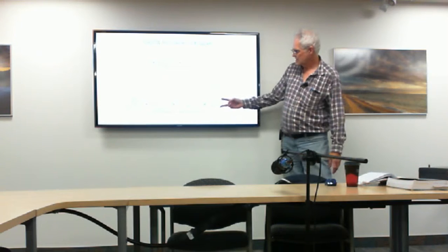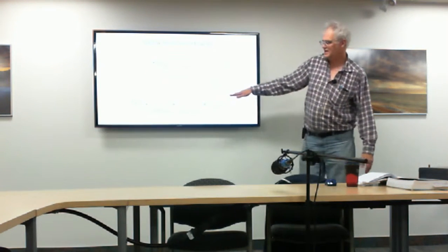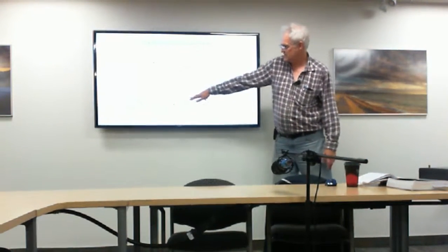Like I said, we use a limiter just to basically chop off any noise peaks, because we don't care about any AM modulation on it. We just want to know what the frequency shifts.